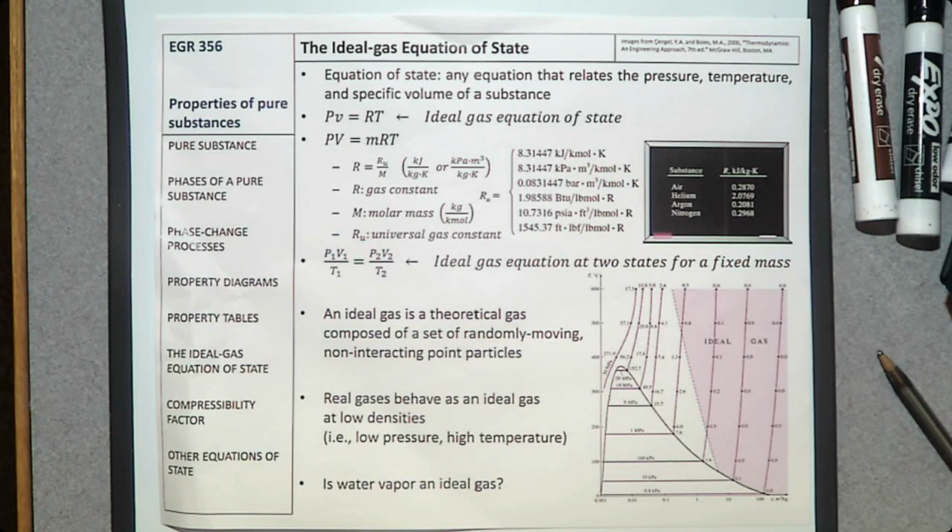If the pressures or temperatures are not available directly, we have to use a linear interpolation to get our value, right? But when we have a pure system that never undergoes phase change during the process, then we can use much simpler equations such as the ideal gas equation, and later we are going to talk about the specific heat equation, okay? So we are going to talk about both of them to see how we can evaluate their properties.